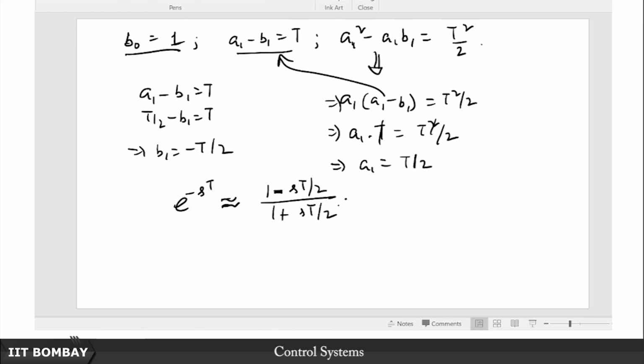Okay. So one final point that we want to discuss in today's lecture before we conclude, and from the next lecture onwards we shall talk about controller design. Of course we've already seen some hints about what a good controller should have. It turns out that if you want stability, a good controller better have some zeros, right? Because we've seen this additional 0 on the left half plane, of course on the left half plane, not on the right half plane.